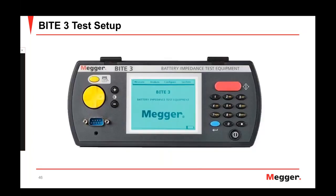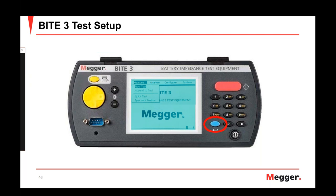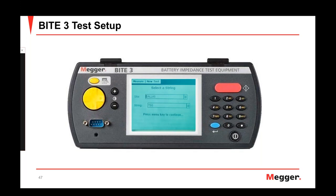So let's now talk about how we're going to set up the BITE 3 to begin the test. To do that, you're going to press the black power on button so that we can boot up the instrument. After we've booted up the instrument, we're going to go ahead and press the yellow menu button to bring up the menu for a new test. Go ahead and highlight the new test function and then click the blue enter button to proceed with the setup. The first thing it's going to ask you to do is to select a site and string.